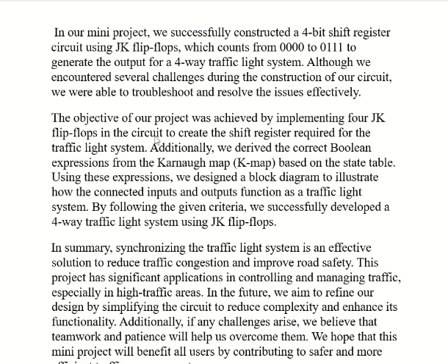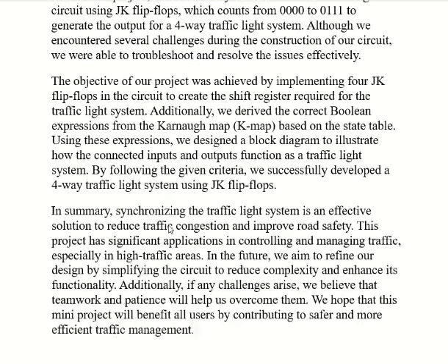The objective of our project was achieved by implementing 4 JK flip-flops in the circuit to create the shift register required for the traffic light system. Additionally, we derived the correct Boolean expression from the K-map based on the state diagram. Using this expression, we designed a block diagram to illustrate how the connected inputs and outputs function as a traffic light system. By following the given criteria, we successfully developed a 4-way traffic light system using JK flip-flops.